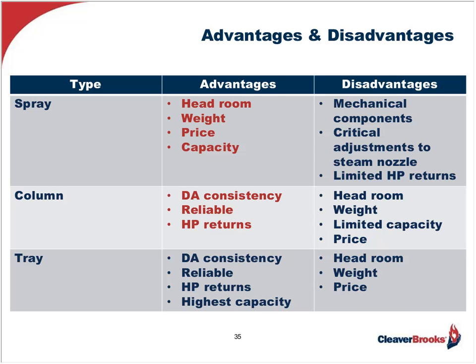And then there's the question of high pressure returns. With the spray deaerator, we're limited to a large extent due to its intolerance to handle certain amounts of flash steam. Not the same problem in the column and tray, as they have counterflow design taking place in separate tanks, wherein flash steam is occurring in the feed tank and does not impede the deaerating process as it might with the spray type.